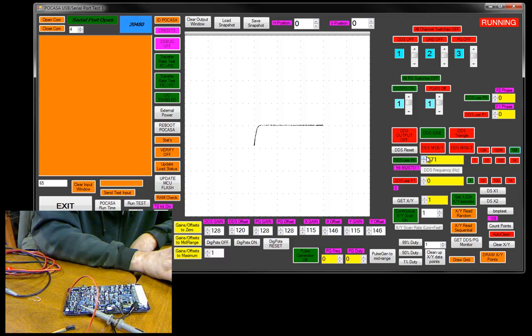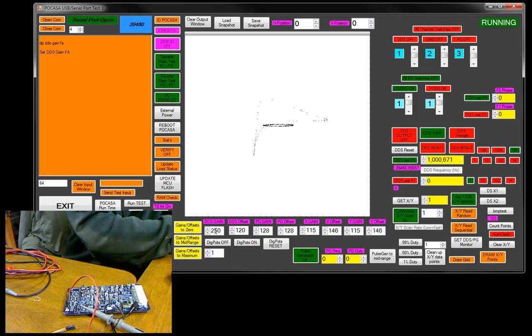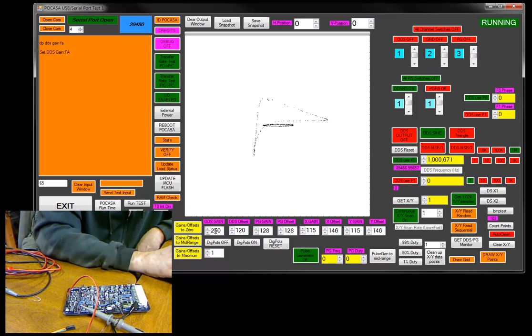Clear the screen quick. A diode. And frequency doesn't matter. Now in this case, there's a little bit of capacitance going on here, so you might see a little bit of a circle kick in. But I cranked it up to 89.5 kilohertz. There's a little bit of a circle, and well, that's all circle now because I don't have enough voltage left over to drive anything. So we crank up the voltage. That's still a diode,